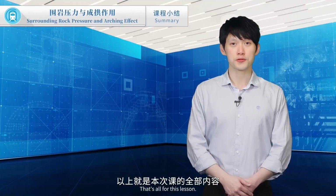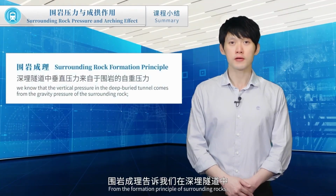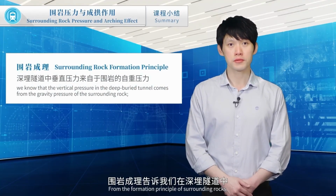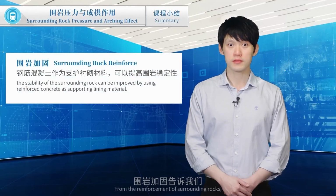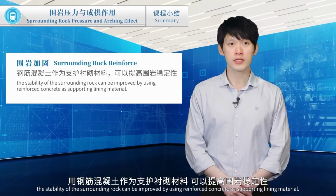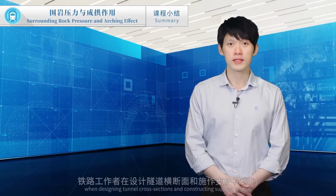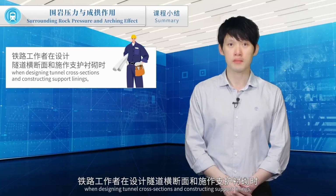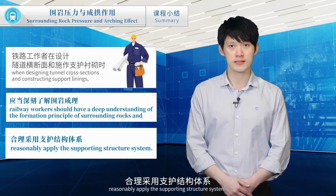That's all for this lesson. Let's make a summary. From the formation principle of surrounding rocks, we know that the vertical pressure in the deep buried tunnel comes from the gravity pressure of the surrounding rock. From the reinforcement of surrounding rocks, the stability of the surrounding rock can be improved by using reinforced concrete as supporting lining material. To ensure safer and more efficient tunneling, when designing tunnel cross-sections and constructing support linings, railway workers should have a deep understanding of the formation principle of surrounding rocks and reasonably apply the supporting structure system.